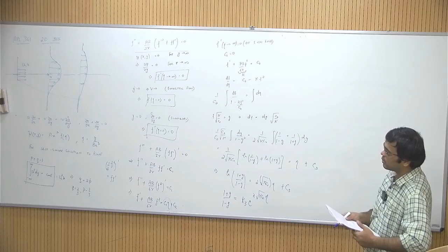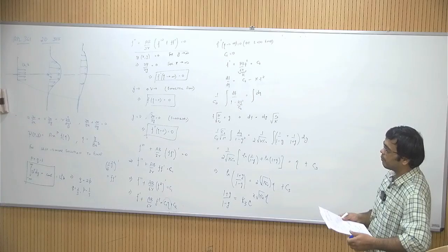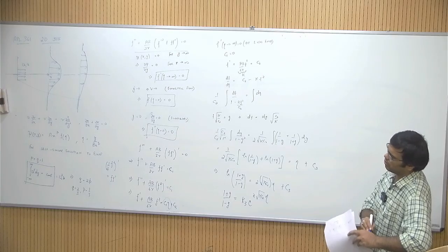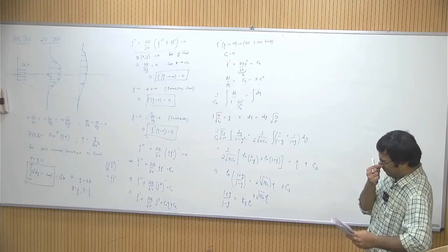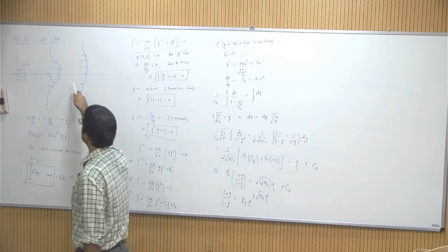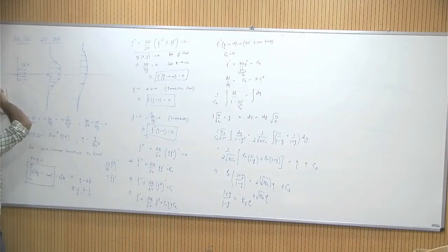Momentum flux. Yeah. Where were viscous losses? So this is not boundary layer, this is jet. Okay. Technically, there is no wall here. So viscous losses is a very generic term. You know, a lot of hand waviness can be done by saying viscous losses. What do you mean by losses? I'm not writing an energy equation. I'm writing a momentum flux term. Viscous losses usually mean loss of energy.